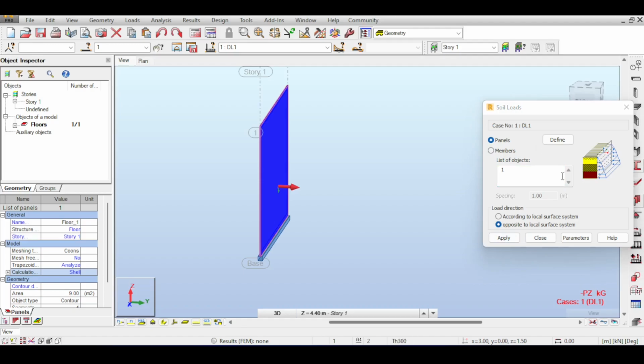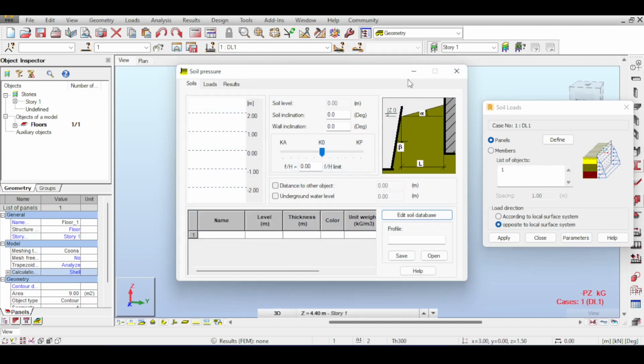The second question is to define the soil parameters used to apply the pressure. So you click on parameters, and now you can see something very similar to what you do in your geotechnical course. The soil inclination is how much the soil behind the retaining wall is inclined, and in my case I'm assuming that my soil is perfectly horizontal. The inclination actually affects how the soil pressure is applied on the wall. Of course, for more information, I highly recommend a reference, which is Foundation Engineering by Braja M. Das. It's a very nice book. I studied it personally back in my university days.